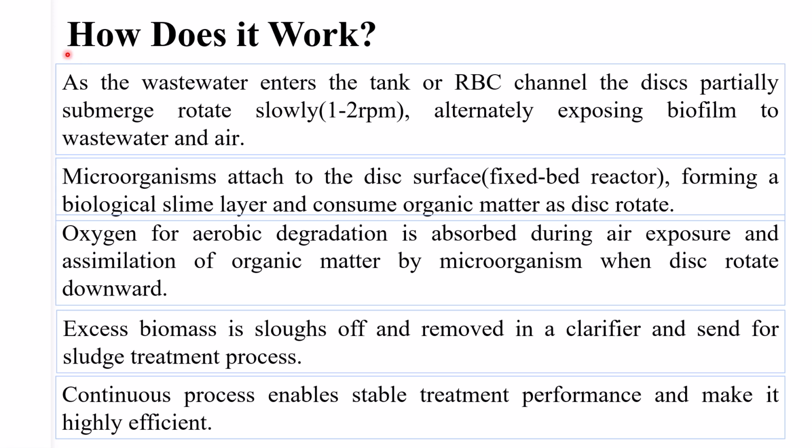So now we will see the working of the RBC unit. As the wastewater enters the tank or RBC channel, the partially submerged disc rotates slowly, alternately exposing the biofilm to wastewater and the air. The microorganisms attached to the disc surface, that is a fixed bed reactor, form a biological slime layer and consume organic matter as the disc rotates.